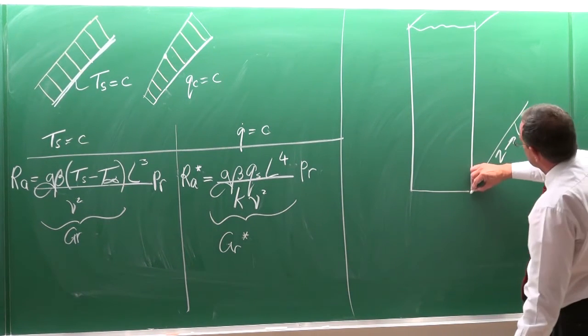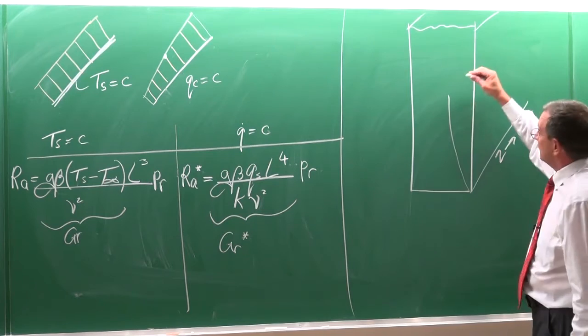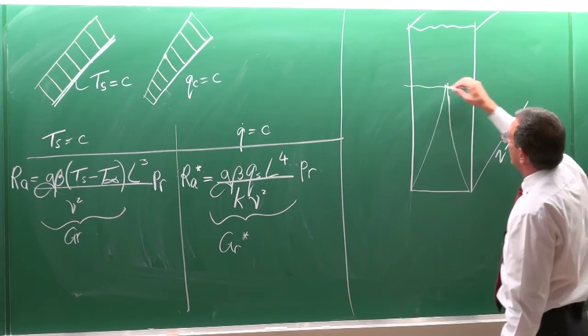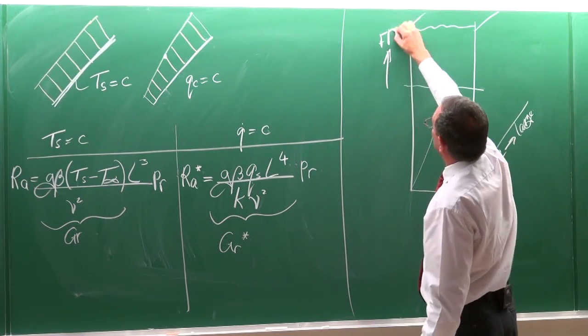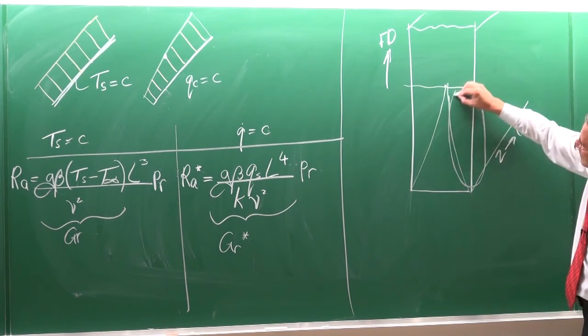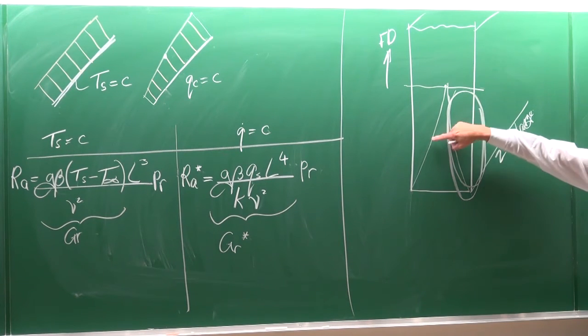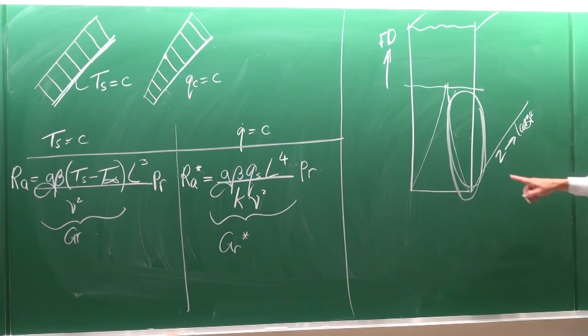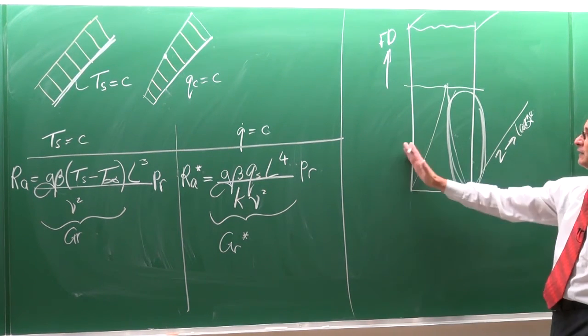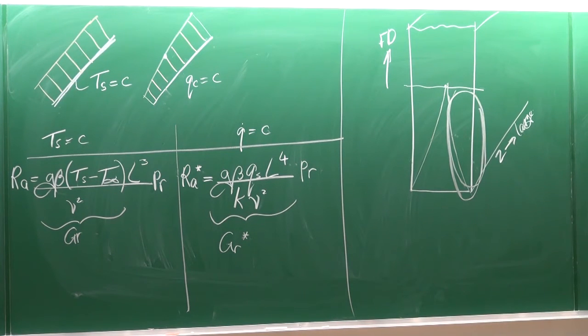What they're going to do is have the thermal boundary layer grow up to that point there. And from there on, we know we've got fully developed flow. But in this region here, this boundary layer is not being influenced by the other boundary layer. So this is a flat plate situation. Just by considering a flat plate, you can get the heat transfer rate from this one and from that one, and you can do your calculations. So remember, small things like this are very important.